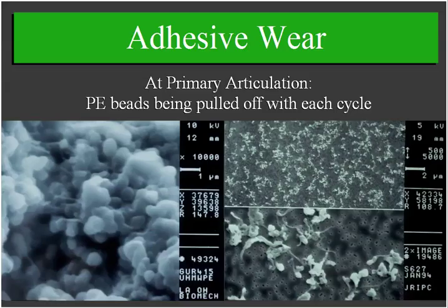And here is the classic example. I got this from Harry McKellop. Scanning electron micrograph of an acetabular cup. And so on the left, you have these little tiny beads in the cup. And if you put this in a wear simulator for 10 million cycles, and you look at the debris on the bottom of that, you see these little beads at the bottom of the wear simulator. And if you look more closely, what you see at these arrows are these little stretched areas of polyethylene.